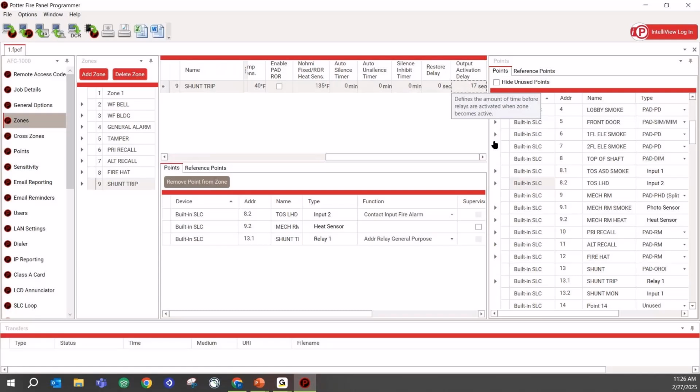I had 20 degrees to start. Now I've added 35 more. So I've got 55 degrees of separation. So I can only go as low as 135. That means my sprinkler head needs to be 190. And he reached out to the sprinkler fitter and said, hey, we need to put a higher value head there. His point was we were going to dump water. If we get to 165, we're going to get to 190. We're going to dump water. But he wanted to give that firefighter a chance. Now, keep in mind, that whole conversation is kind of antiquated today because most new elevators come with a battery backup built on the roof of the car.